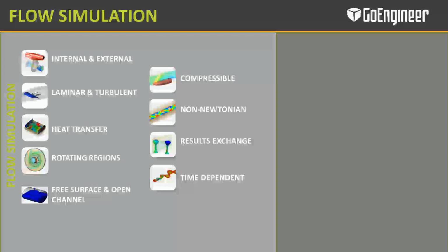And hence our problem right now is a steady state problem, because we don't want the thermal profile to be acceptable after just 2 hours of usage, right? And if that was the case, we could have done a transient analysis to check the response for the first 2 hours only. But what we want is a steady state response for complete time.